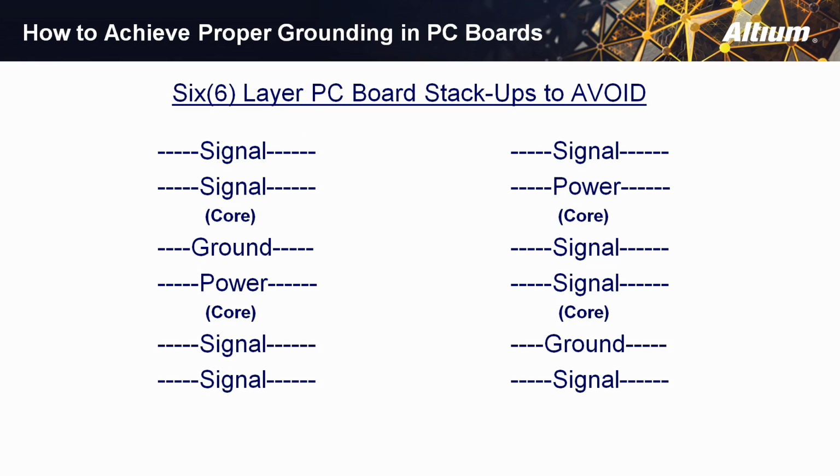What else is occupying that space? The fields from signal lines on layers 3 and 4. So as those signals are generated, their fields also occupy the same space as the fields that are delivering power, which means they induce currents into one another that create coupling of common mode currents into the signal lines and noise coupling into the power energy driving the IC.